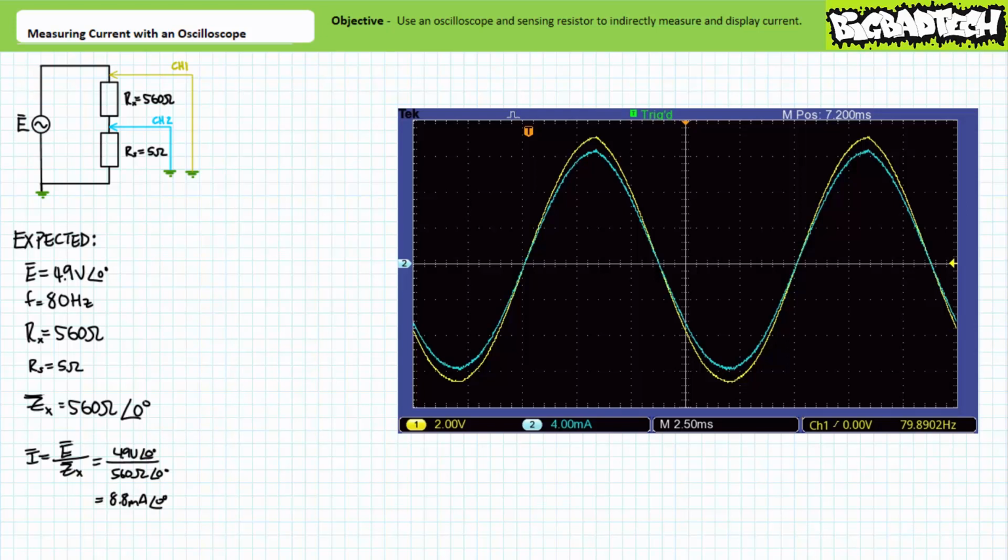The two waveforms are obviously in phase with one another in that the direct means of measuring and displaying voltage across the resistor, channel 1, simultaneously peaks and valleys with the indirect means of measuring and displaying current through the resistor, channel 2, indicating that our resistor is obviously wholly resistive in nature. This is the larger take-home point. There exists no relative phase shift between the voltage and current for this resistive element.